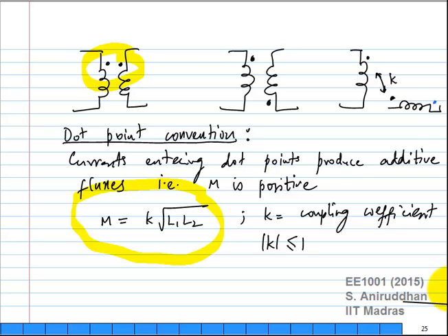If you have partial coupling, where only part of the flux cuts the other coil, then K is less than 1. So if you are trying to create a transformer, where you want the coupling to be as tight as possible, you build it in a specific physical configuration to make sure the flux cuts it as much as possible. Is that clear?